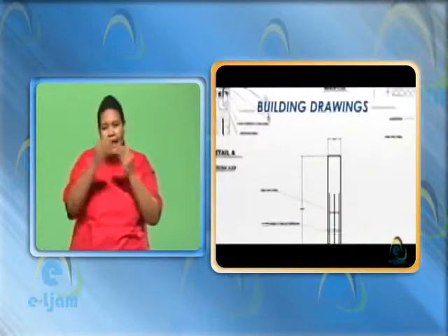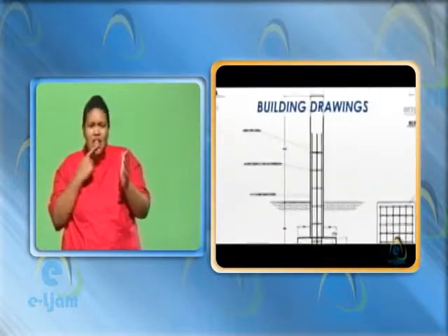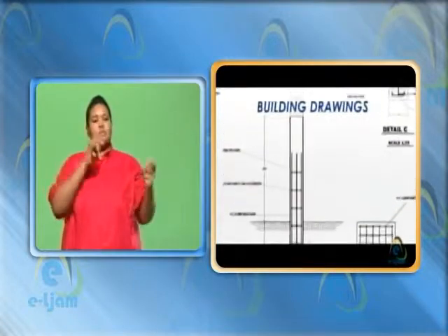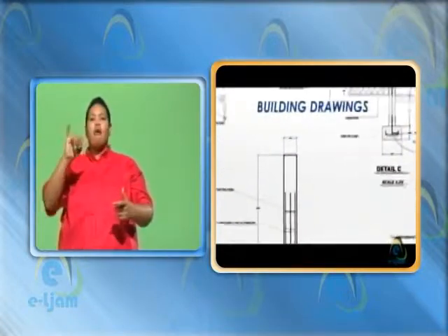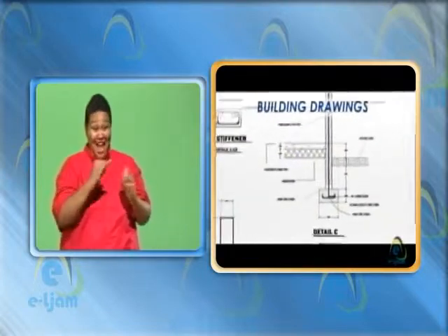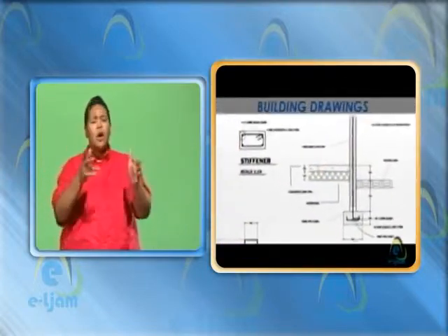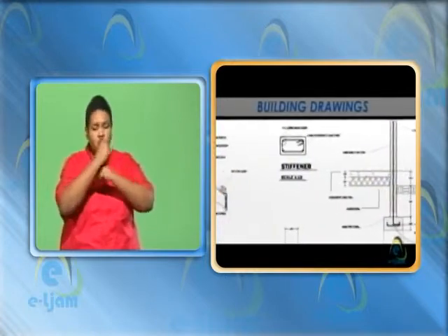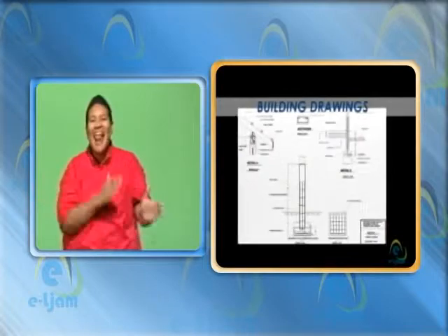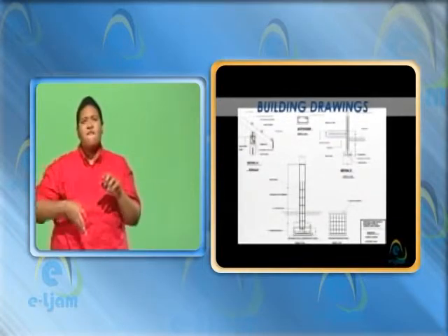Details. These are drawings that show a small part of the construction at a larger scale, to show how the component parts fit together. Section drawings at large scale are a standard way of showing building construction details. A full set of construction details need to show plan details as well as vertical section details.